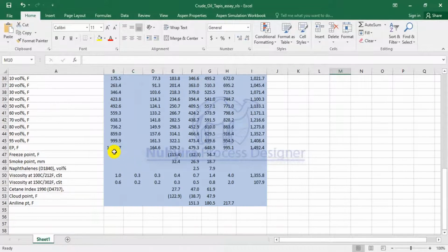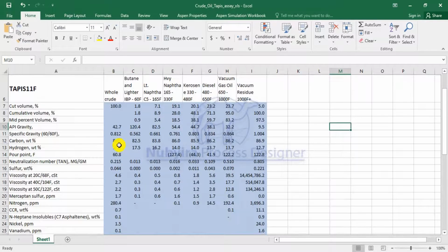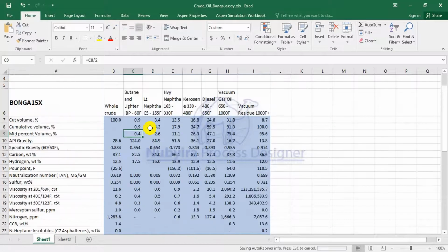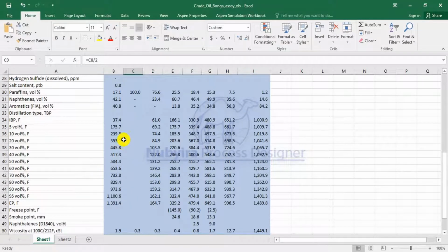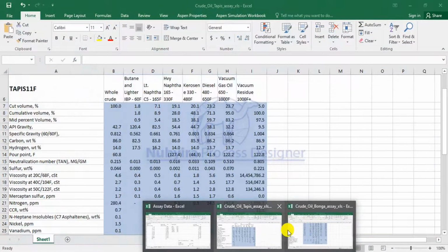this is like a low boiling crude. You understand, the last boiling point is 1352.7 Fahrenheit, while the API for the crude is 42.7. You can see, very light. And for this, 28.6. So this is like a medium crude, and this one is 1394. That's the last one. Okay, so I had to just copy all this data that I needed, because you can't